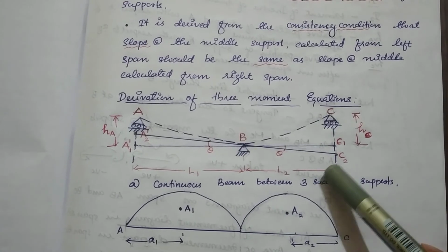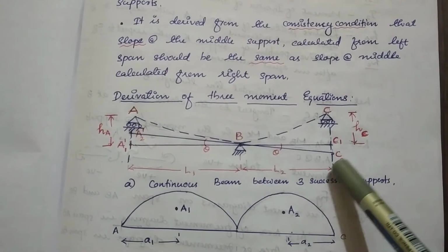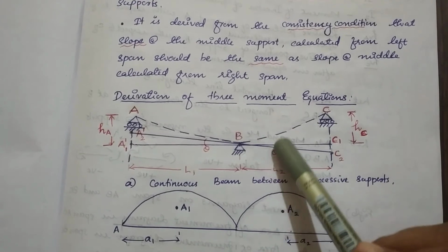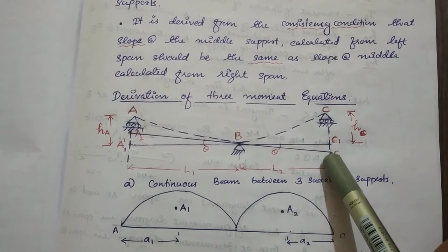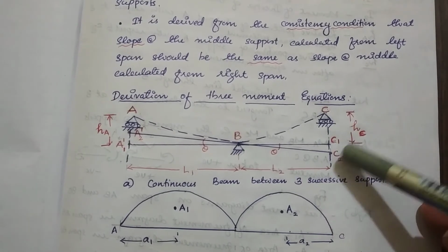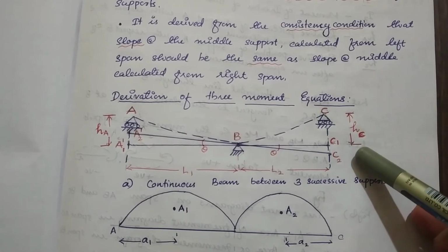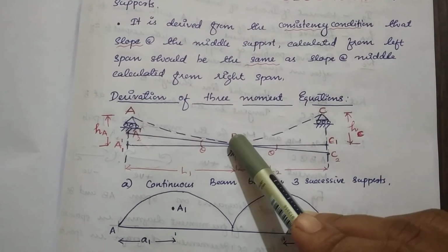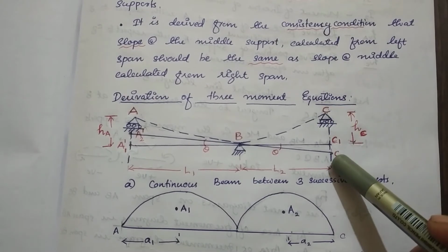Okay. Similarly here, the tangent of B makes at C2, and theta is equal to C1 C2 divided by L2. Here we want an expression in terms of HC, so we can write C2 minus HC, where C2 is the tangent, so C2 is the deflection.